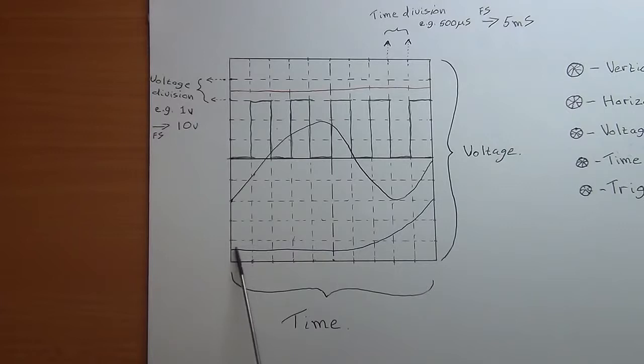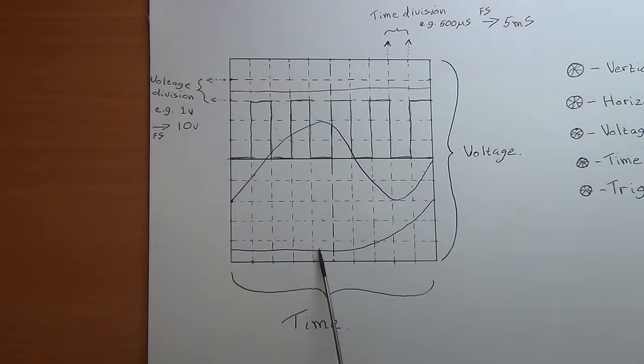Then over here, what I'm showing is you could, let's say we hooked this up to a capacitor that was charging over time. And as you connected the capacitor and you had a battery or a variable power supply attached, if you set your time base slow enough, or even if things were happening fast, you might see a signal like this, where the charge voltage is initially low in your capacitor, and then it starts building up over time. And that would perhaps be the trace or the signal representation you would actually get on the screen in that case.